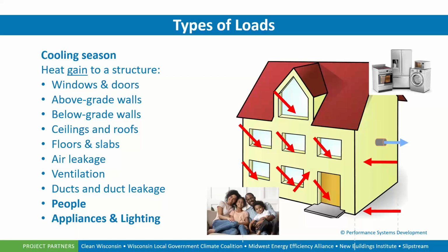We can also assign appliance loads for kitchens, laundries, entertainment centers. We have a movie theater or a room, or a home office. We can add additional load into sensible load requirements in our Manual J calculation, so that's taken into account. Because if you think about the amount of computers and monitors and LED TVs, all these are giant radiators putting heat into the structure. So we take that into account so that we have that additional heat load accounted for.